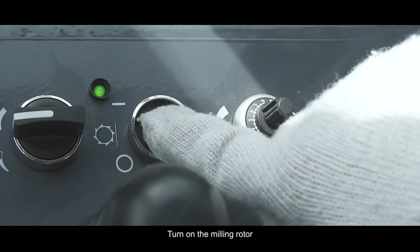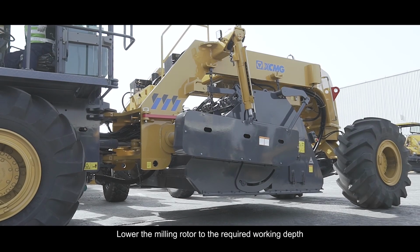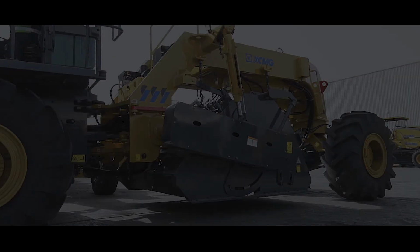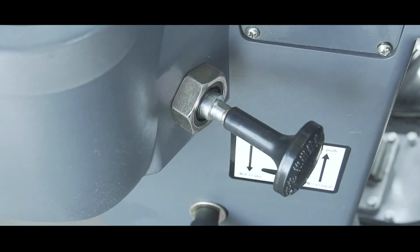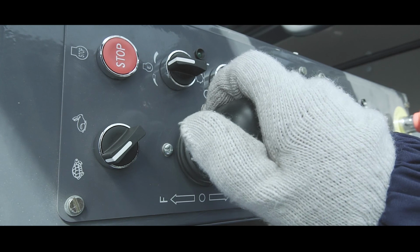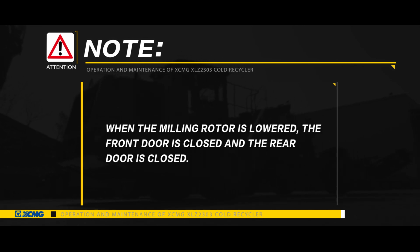Turn on the milling rotor. Lower the milling rotor to the required working depth. Select the walking gear as the working gear. Release the parking brake. Drive the machine forward and walk slowly. Note: when the milling rotor is lowered, the front door is closed and the rear door is closed.